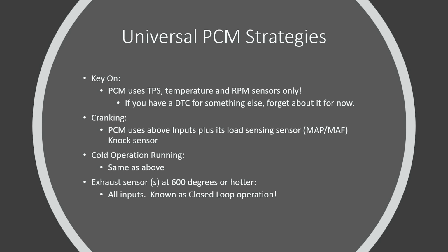That, for instance, we all heard of open closed loop or limp mode. Those are two very popular ones. Clear flood mode, that's another popular one. But we have startup mode, we have different modes of operation. And we'll use the startup mode as an example. Let's say the customer brings you a vehicle and they say, hey, this thing's hard starting or it has poor performance as soon as I start it up. But as the vehicle warms up, it's fine, the problem goes away.